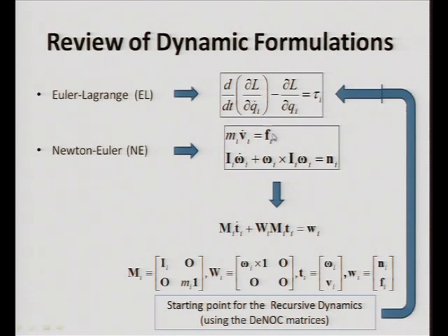If you are choosing some other body, this expression has to be different, please remember that. Now, both have their advantages and disadvantages. For a rigid body, the Newton-Euler equation will lead to 6 scalar equations. The first 3 are the linear equations of motion, and the last 3 are the rotational equations of motion. So, if for our robot suppose 6 bodies are there, 6 into 6, 36 equations will be generated.